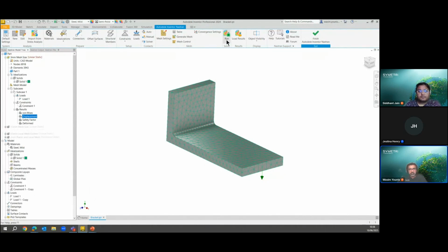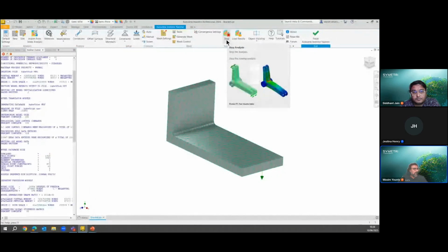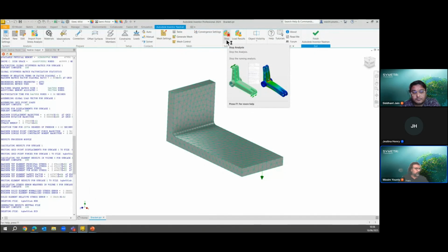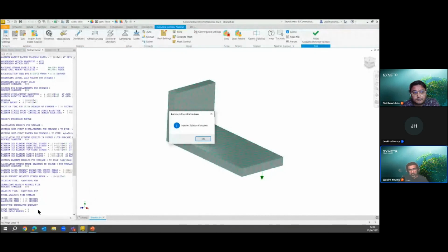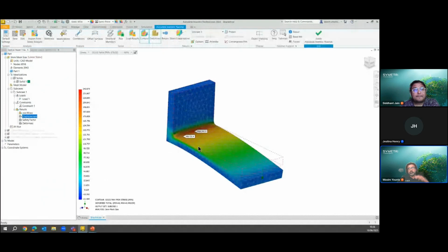I'm going to run the analysis. And what we'll see here is I want to see a stress value. So we had about 194 or something. And what I love about Nastran, I'm not sure if this happens to you guys, is when you run the analysis, does anybody get 0 warnings? It's a nice feeling. When you, yes, I know. Start putting contacts in there, but do not try to keep doing something on Nastran to get 0 warnings. They're not critical. Now you see there, I have 242, and the stress value max principal is on the bottom of the fillet. So that's fine.